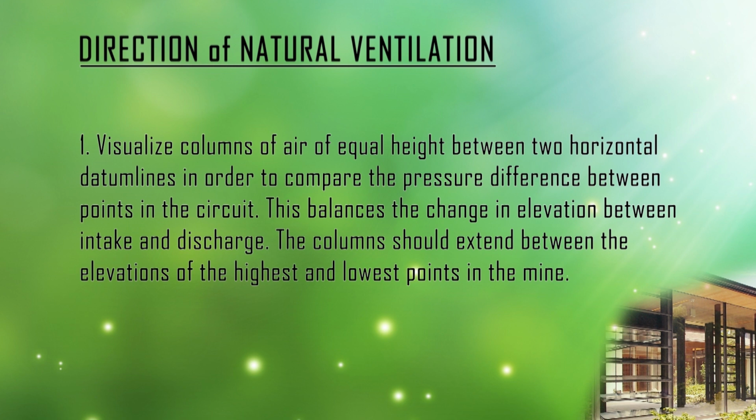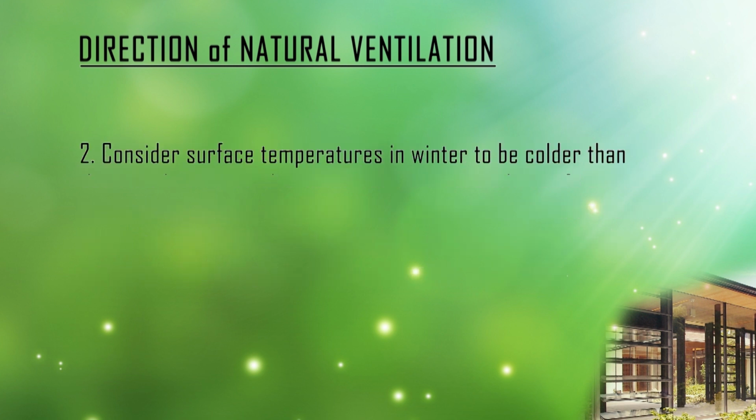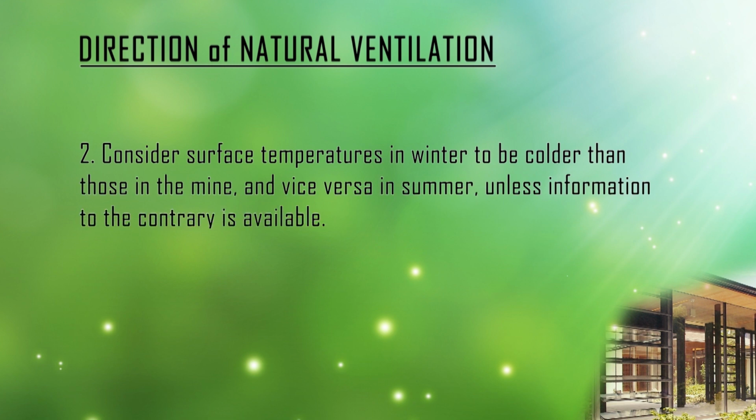If both the shafts are at the same level, then the balance of change in elevation between intake and return, the column should extend between elevations of highest and lowest points in the mine. Consider the surface temperature in winter to be colder than those in the mine, and vice versa in summer, unless information to the contrary is available.